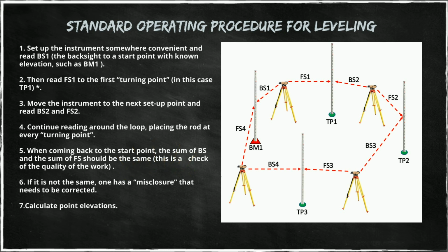If this misclosure is too large, then we have to repeat these measurements. If it's acceptable, then we can find a way of adjusting these readings for the purpose of coming up with a zero difference here.